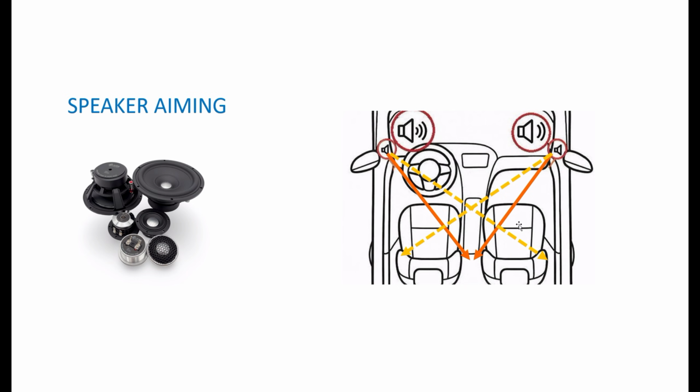So you can do it either way. As I said, it's a bit of six of one, half a dozen of the other, because for me, this is more of a compromise in terms of the on axis for both passenger and driver, and this one just moves the focal point kind of forward. So you can do either, but that's how those two stack up. So that is talking about tweeters and mids up on the sails and pillars.